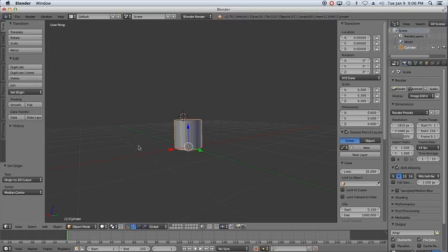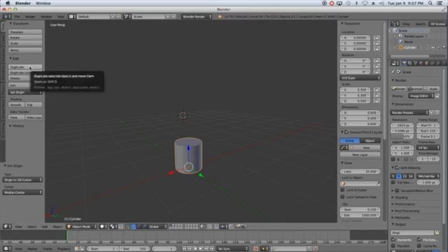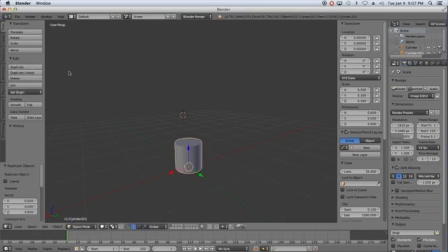All right, a second thing that you can do for this kind of project is to make a hole in this, if I want to place a hole for a carbon fiber rod to go in. And I'm going to do it like this. With that object selected, I'm just going to go over to duplicate. And without moving the mouse, I'm going to click twice. Duplicate, duplicate. The first one duplicates it, and the second one, if I move the mouse, would move it to a different position. So now I actually have 2 of these cylinders in this exact same location.